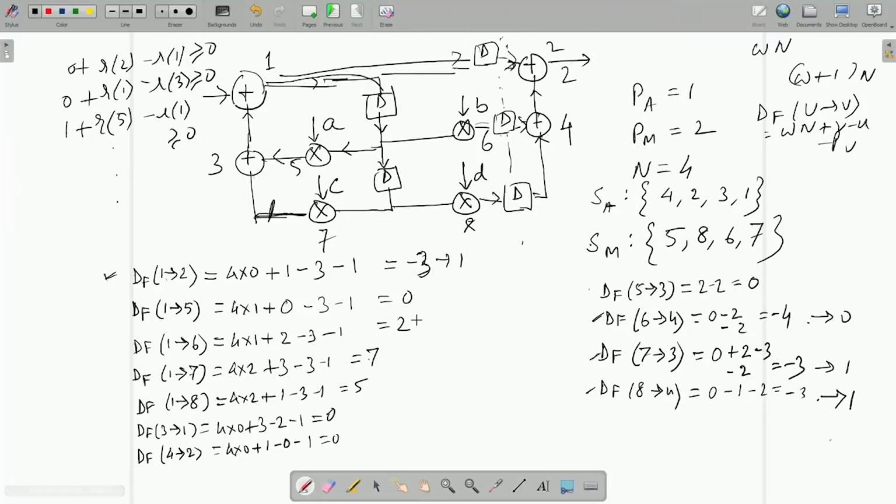So, fine. Here I just added delay from outside; there was no delay present here, but it is forward path pipelining, forward path retiming. I just added delay, and they form a cut set, these 3 edges. If you cut them, the entire DFG is cut into 2. So, for a valid cut set, only one direction. So, I happily add a constant number of delay, one delay in all of them.